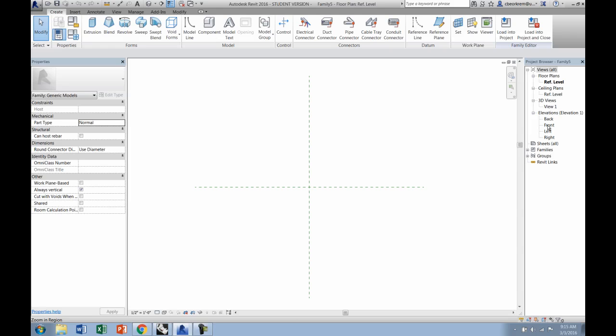As we're modeling things, we're almost always going to be using extrusions or sweeps and actually a blend. You have to be conscientious of the surfaces that you're modeling on and the orientation, right? Everything needs to maintain some kind of rigorous orientation to the surface of the curtain panel. Again, that's going to be the glazing surface.